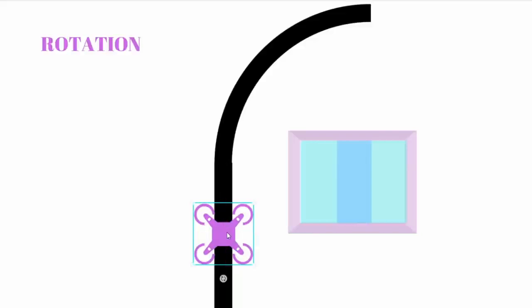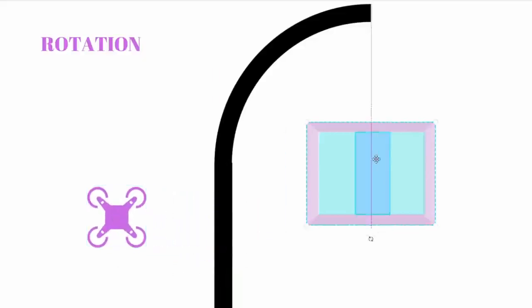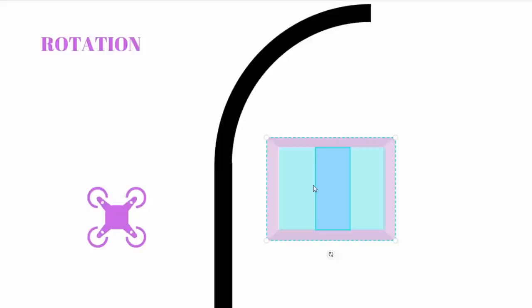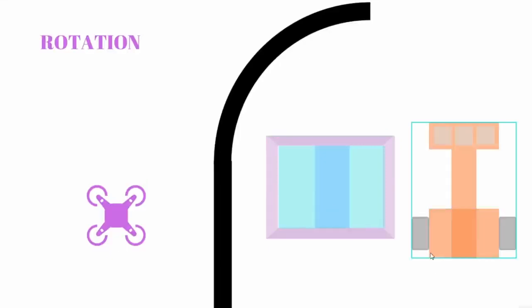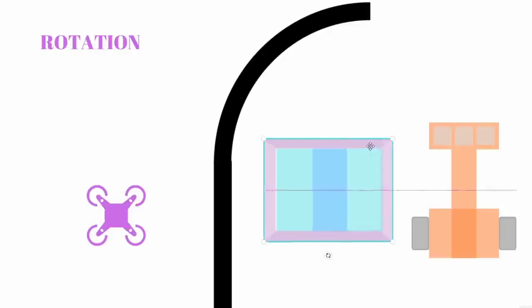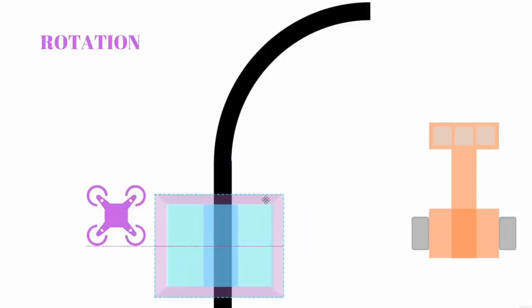We are viewing downwards, and what we will get is an image. We will split this image into 3 different parts: left, center, and right. This will be exactly the same method as our line follower. Like this line follower had 3 sensors, in the same way we will have 3 regions where we will detect our black line. When we get the image, if the line is in the middle, then we will say go forward.